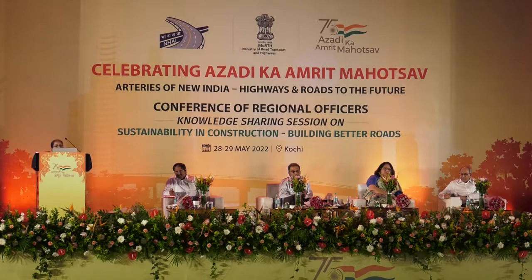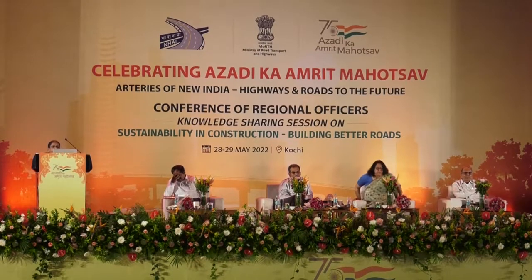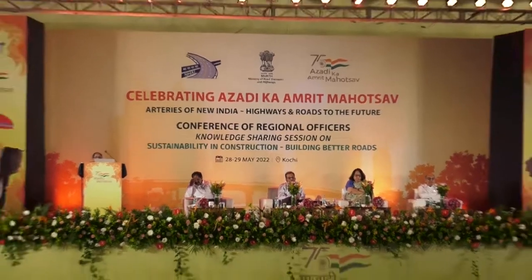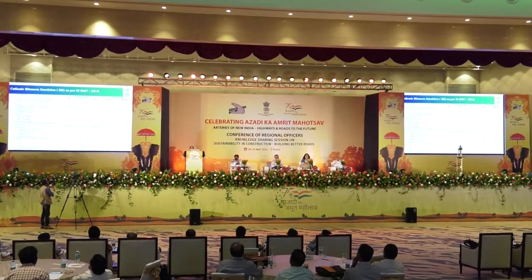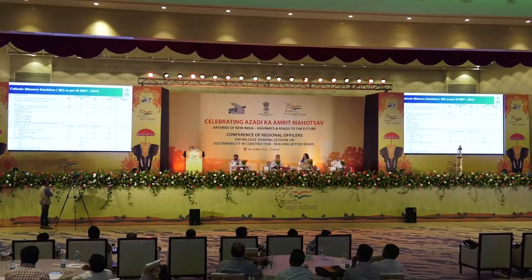Limitation of this product is that it can be used only for the low loads area and low traffic roads when we are talking about the complete roads on it. But of course, when we are talking about the applications, it can be used for tack coat applications, surface dressing. Medium setting grade can be used for road mixes and for surface dressing. Slow setting bitumen emulsion can be used for crack sealing and prime coat and cold mix applications. These are the typical cationic bitumen specifications from IS 8887 2018 version.